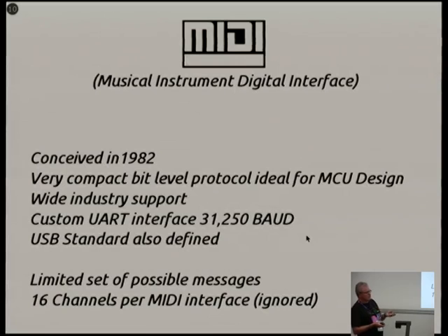Ideally designed, if you're building a little microcontroller type circuit, really good, because it's also designed so that you get as much information up front rather than later on. So you can make your coding decisions very early on without having to hold a big buffer of information. When you're designing on a microcontroller with 8K of RAM, those things become quite important. Wide industry support: virtually all synthesizers and outboard devices have some form of MIDI control built in. Traditionally, it's 31.25 kbaud. From a hardware point of view, it looks pretty much like a serial port. And as I said earlier, there is also a USB standard.